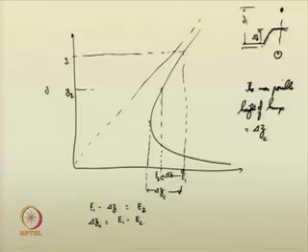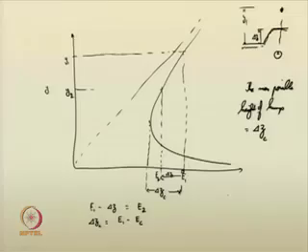E c, it is quite clear how to evaluate it for rectangular channels. You know that the critical conditions are not dependent on the geometry of the problem for critical rectangular channels, and you have already derived those things. So, E c you can evaluate, and E 1 minus E c will give you the maximum height of the hump in which the upstream conditions are not affected.